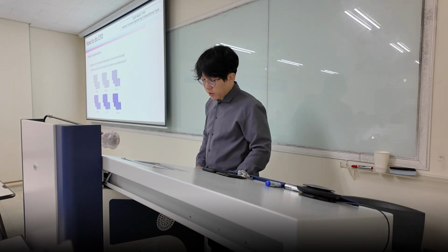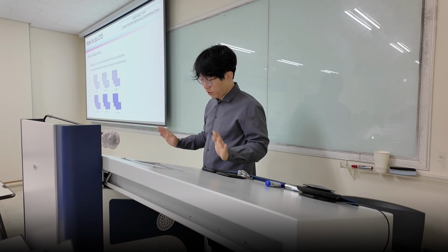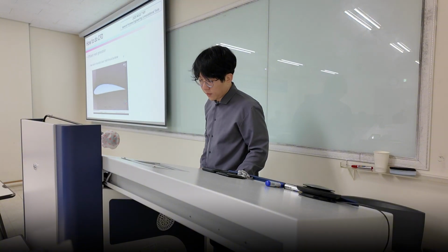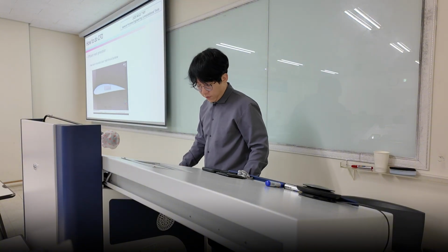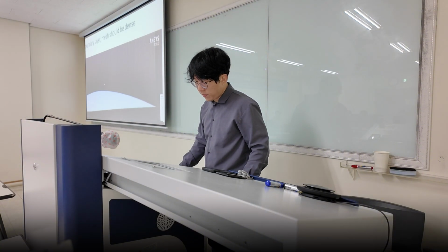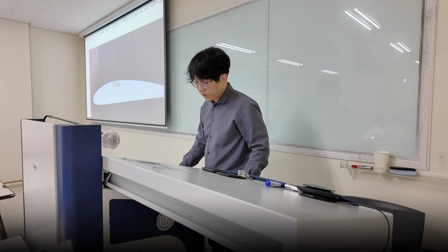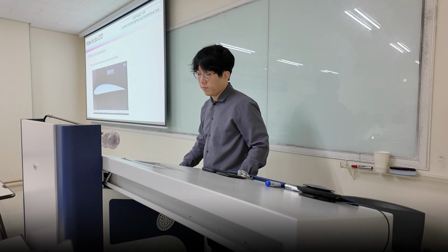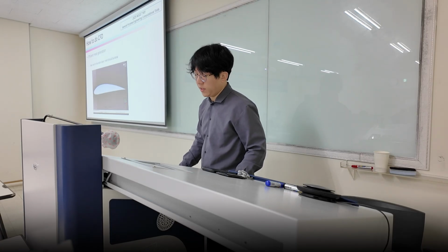And yeah, this is the mesh independence. If you're missing this out, please make sure you supplement this when you're writing a paper using CFD. Yep, you can see for this airfoil shape, the resolution is a lot higher around the object. It's almost black here, but near the wall or boundary layer, the mesh should be denser.